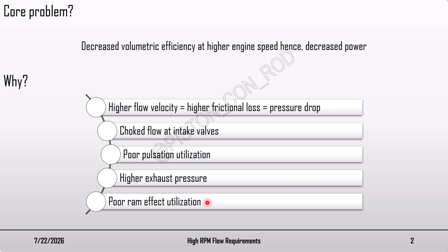So if you choose the intake valve closing timing properly, you can utilize this by closing the intake valve at a later phase, which results in higher volumetric efficiency and much more air being inside the cylinder. And because of that, you can get more torque and power.